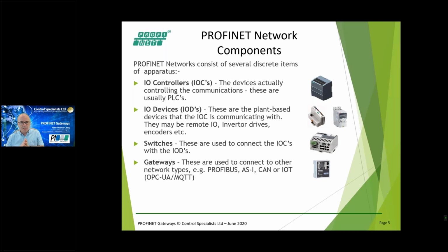You may have a situation where your responsibility is to create a relatively small network on some kind of process control skid that ultimately is going to connect to an existing PROFINET network. So rather than asking for access to their existing PLC configuration, you can create your own network based on your own I/O controller, and then you can agree with the system integrator responsible for the site to link the two together. Basically there is complete isolation between the two, very, very easy to set up.